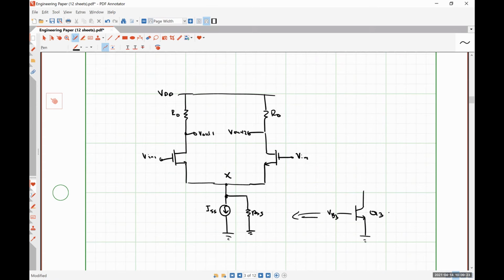Correct, yeah. If it's perfectly symmetrical, correct. But as soon as we add a mismatch, then we have common mode conversion gain happening. So differentially, it behaves exactly like a simple differential pair. The voltage gain is negative gm times RD. And I'm saying it's gm times RD because in all of these common mode problems, we have been neglecting either the early effect or channel length modulation in our lower pair.